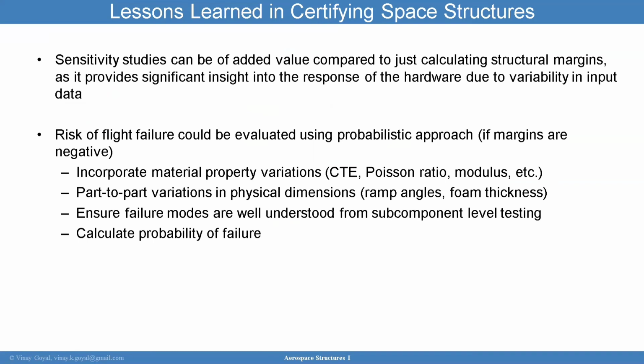Sensitivity studies can be of added value when compared to just calculating structural margin. If you just calculate structural margin with nominal properties, it gives you very little information about what is going on. But when you do a margin calculation and study what parameters affect the margin, like modulus, thickness, what things matter, I think at those points in time you learn more about how the structure responds. So sensitivity studies can be very valuable, especially if you use shell elements or beam elements, where you can quickly change thickness and quickly change modulus.